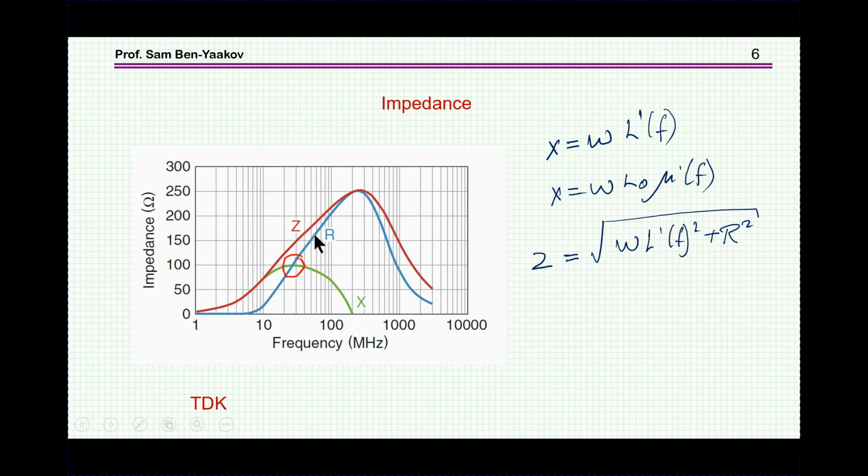Now, the resistive part is again going up with frequency, and this is a very important crossover in which the resistive part is larger than this inductive part. Now, the sum of these, of course, has to be in a phasoric way because there is a 90-degree phase shift between these. The sum here is this total impedance, which is this outer curve, the sum of these two. This is the total impedance that you have of this element.